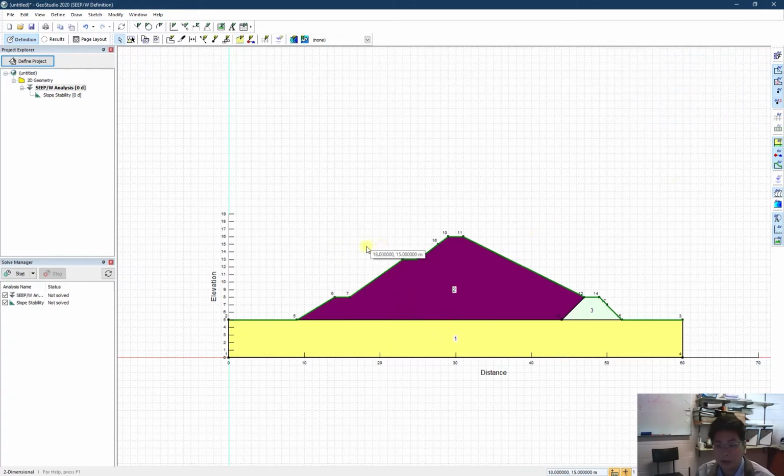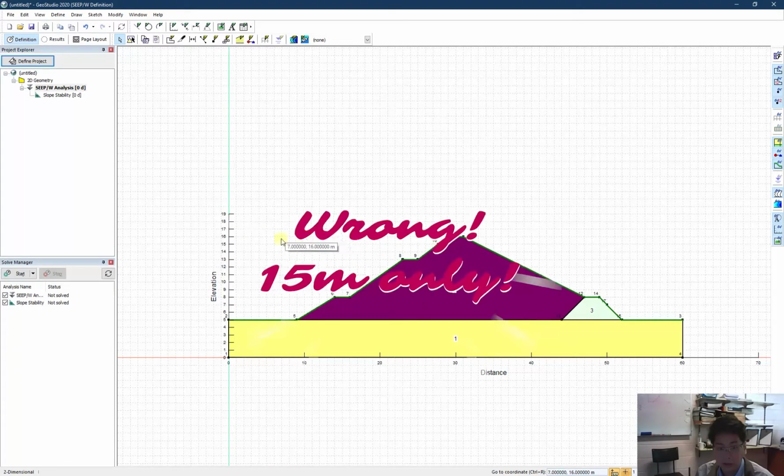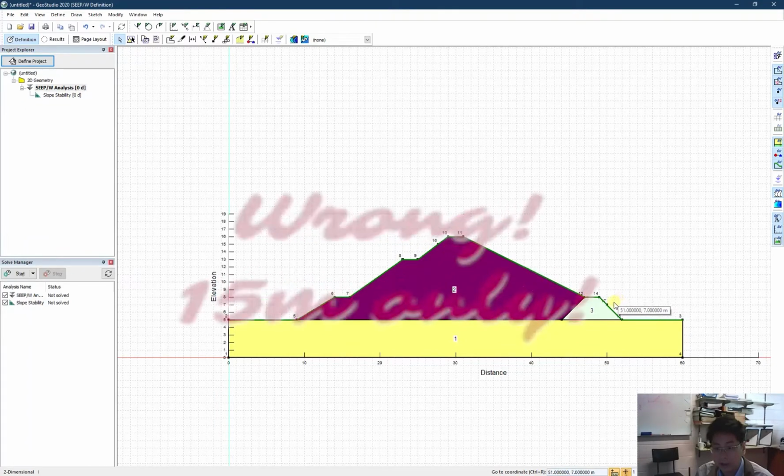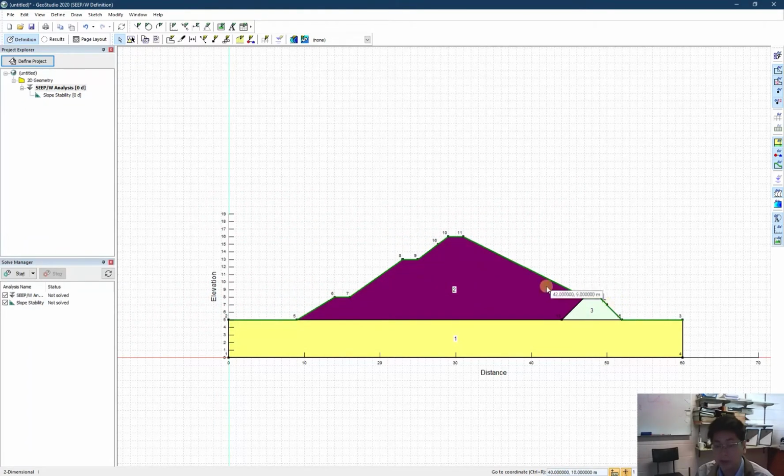Now, the last thing is adding the boundary system. So I need to add up the hydraulic boundary conditions. And I have the water table start from 28, it comes from the reservoir at point 16 and gets out the dam at point 17.